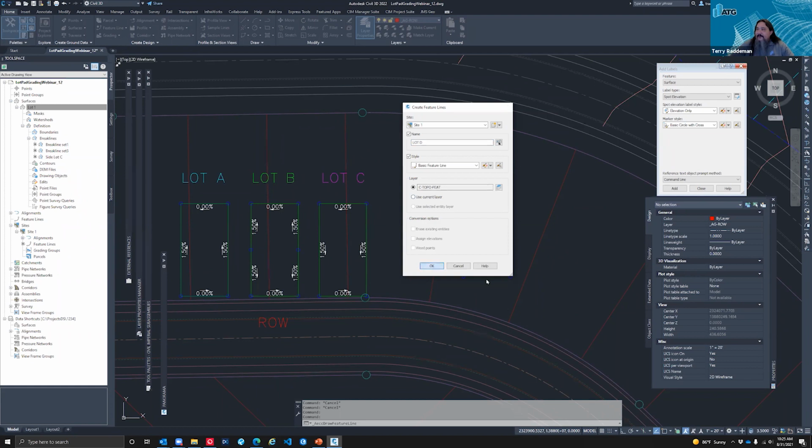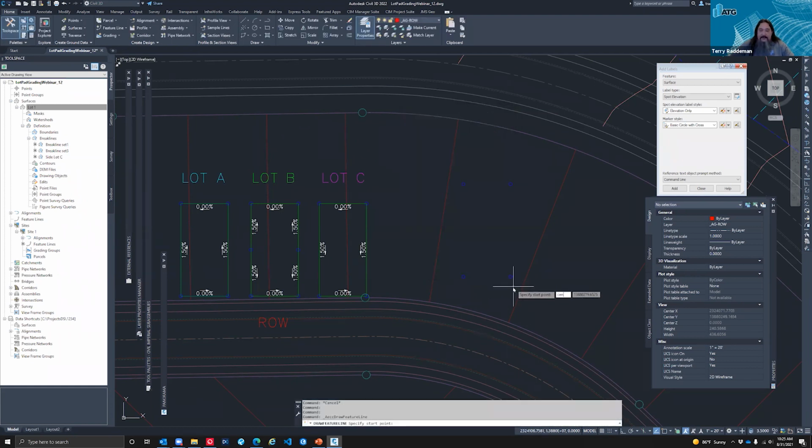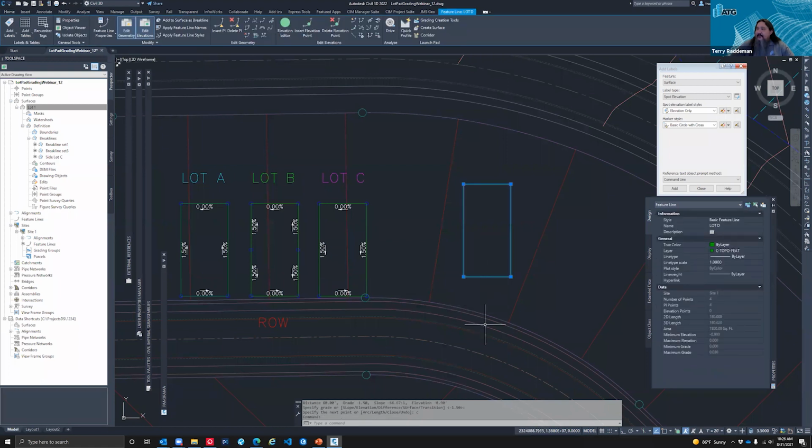That layer is good, and I'm going to go from this center point here, and we're going to go at 0 elevation for now, and we'll look at how these are affected here when we apply them. Basically, it's relative to the surface, and if we have an elevation that is above the beginning of our lot, then the slope is going to change when we do our offset for that.